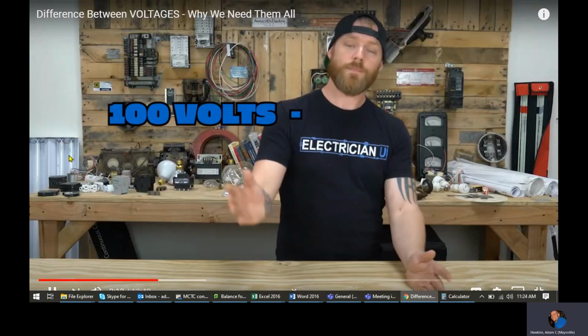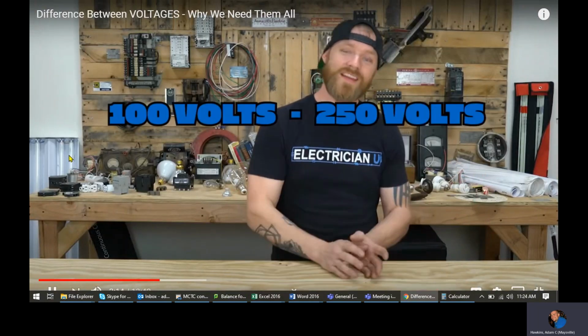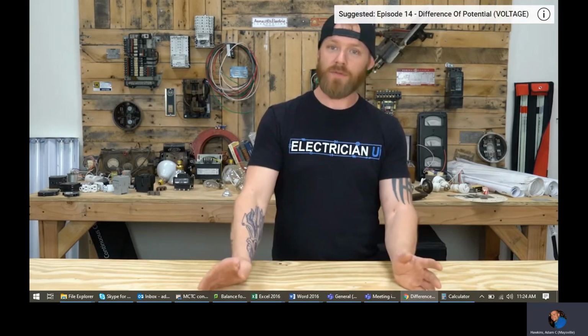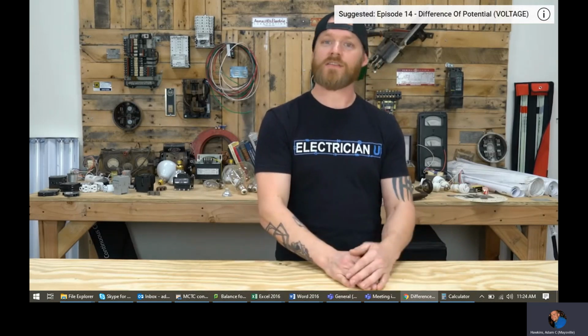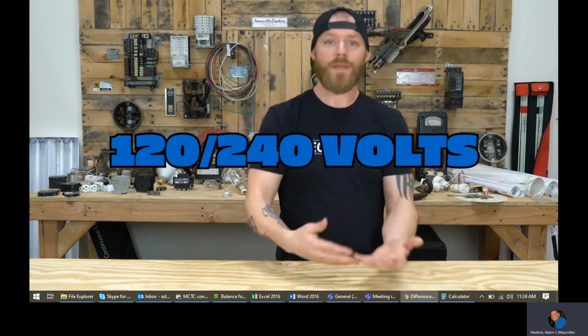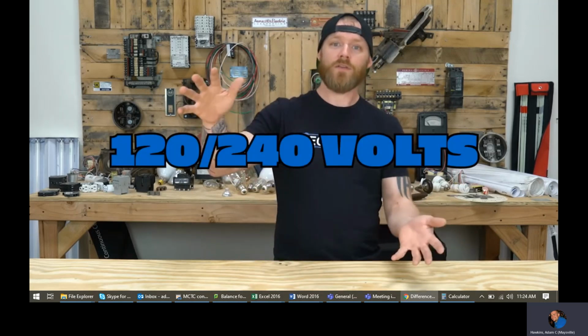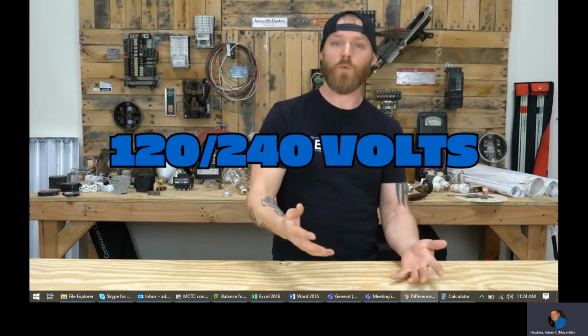So next we're going to talk about voltages between 100 and 250 volts. This is kind of the next class of voltages that you're going to come across, both in single phase and three phase. So in single phase, you're going to come across systems that are 120, 240, and that makes sense, right? You've got 240 volts, and when you cut it in half, you get 120 when you have a neutral present. Otherwise, all the motors and machinery would just run off 240 volts. But the math makes sense how you get from 120 to 240, right? It's just cutting it in half. You're cutting your voltage in half, less pressure.